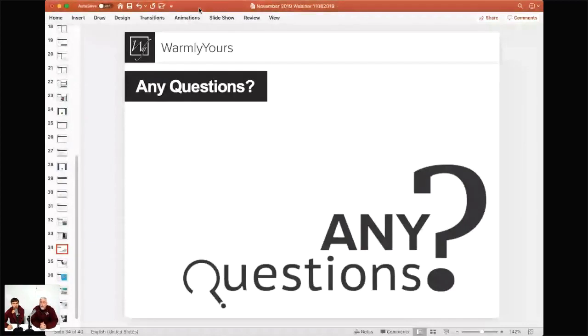Matt is asking, why does the integration kit with floor sensor not work with the Nest Thermostat? So the answer is pretty simple. It all depends on the thermostat of your choice. Nest Thermostat simply does not support any external or floor sensors whatsoever. So you would just use an integration kit with a Nest Thermostat if you want to. But again, there is no sensor connection there. So you can't control the floor temperature if you have no way to connect a floor sensor to the control. So a Nest would be a good pairing with a tile floor, because there's no limit on the tile floor how warm it can get.